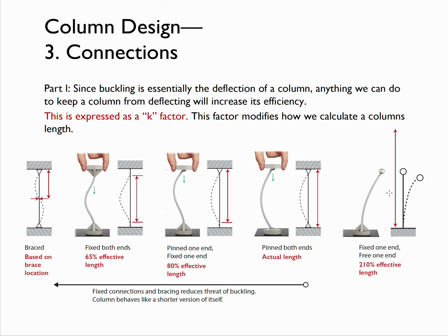So the third factor, besides its shape and material, is connections. This is kind of hard because we haven't gone through connections very explicitly, so I want to make sure and take a little bit of time with this slide. We have always assumed that things have pinned connections as it is now. If we choose different types of connections, whether those connections are fixed or whether they're hinged or whether they're free, it's going to change the behavior. Because all those different things are possible, whether something is braced or fixed or pinned for columns, that then changes how the column will behave.